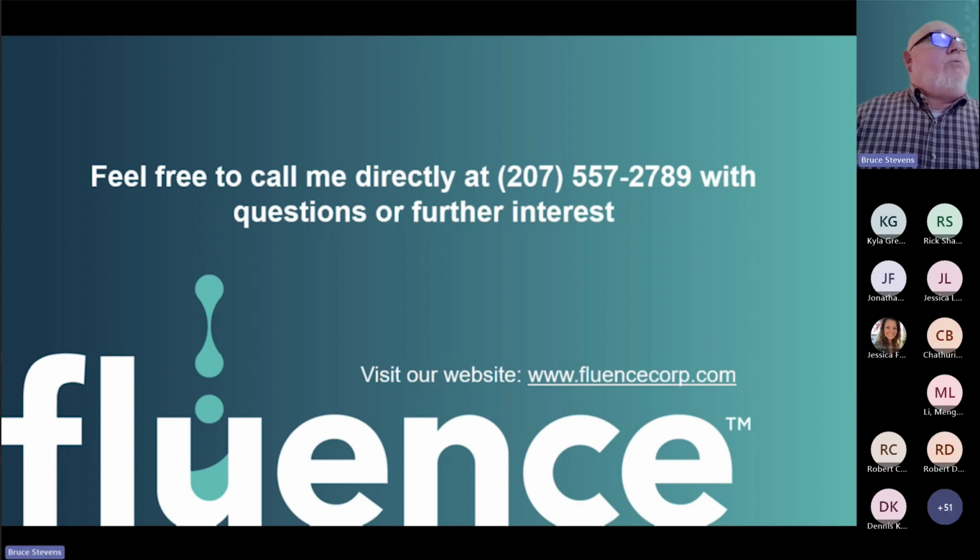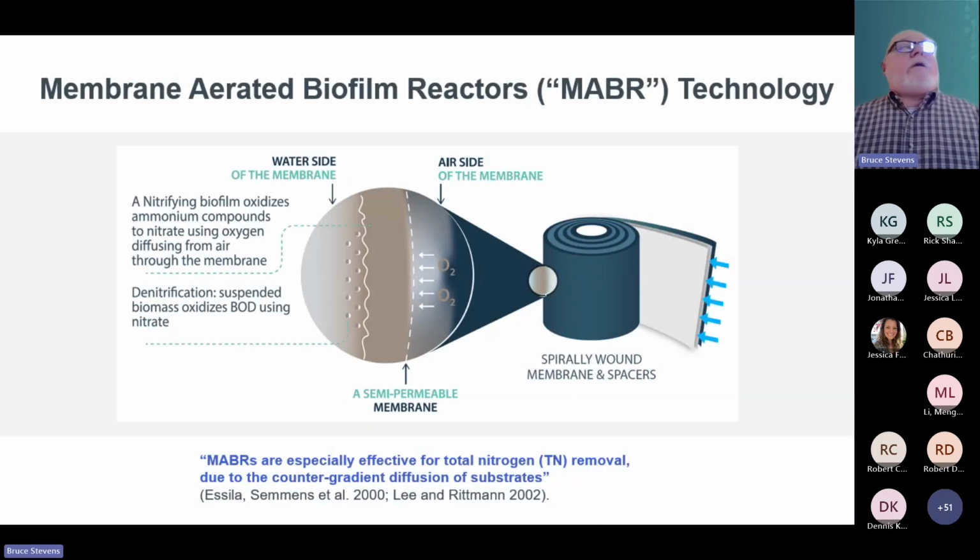So when you look at the membrane, as I said, it's set up to only allow the oxygen molecule to pass through. It's a semi-permeable fabric. So the biofilm growing on the opposite side of it absorbs only pure oxygen. The nitrogen gas that's in the ambient air, the CO2 that's in the ambient air, and any excess oxygen that isn't consumed by the bacteria flows out and up to atmosphere. So that's the way the system works.